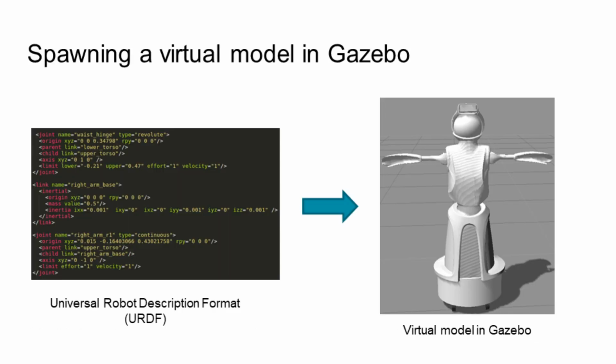We use the open-source software Gazebo as the environment for our simulator. Gazebo is a popular robot simulator that has already been used to simulate robots frequently used in HRI research, including Pepper and Nao. A Unified Robot Description Format, or URDF file, is used to describe the virtual model of Quori, containing information about the various links of the model and their associated masses, inertia matrices, and joints. This information is extracted by the engine and used to render the robot in a 3D environment, as well as to simulate physical forces acting upon it and enforce collision checking.